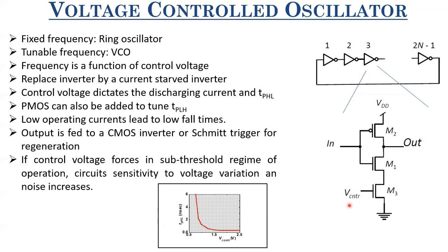The general rule that foundry people or circuit designers employ is, whenever you are working in the subthreshold regime, if a variation in the normal mode of operation, like in the saturation mode, leads to X times change in your output, then in the subthreshold regime it will lead to at least 10x change in the output.